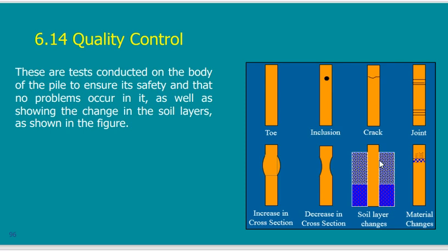When I have a problem with my stomach, I go to the physician and he tells me to do an ultrasound, something like a sonar that you all know. What is this ultrasound? Ultrasound is a test. They put something on my belly, and a wave will penetrate, and the wave will come back again. They analyze this wave and tell me what is inside. We do the same for the piles. We put a wave on top here, and this wave will go down and will be reflected up, and I will collect it again. Once I collect it, I analyze it to know.